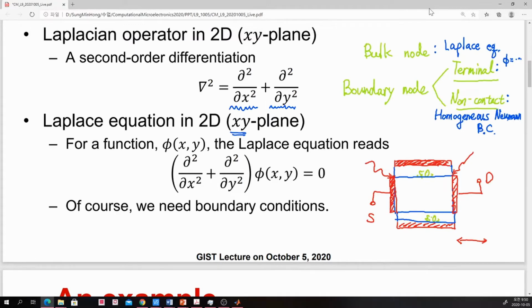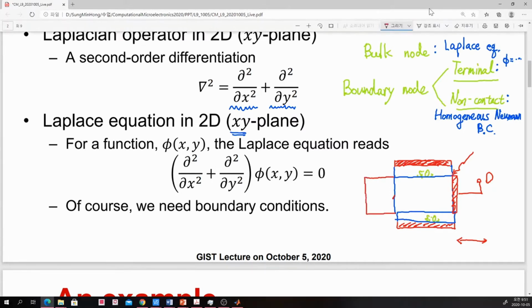So your solution will have a very bad performance or bad physical description about the solution. So the thing is, now you have to think about what is the position of our source contact and drain contact. Then we have no predefined way, but anyhow the position of your source contact should be placed not to disturb the behavior at the source side end of your channel.